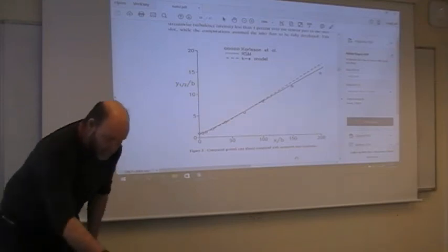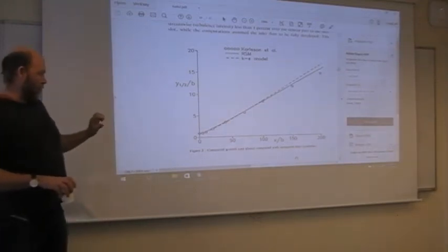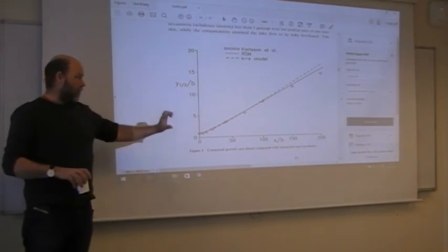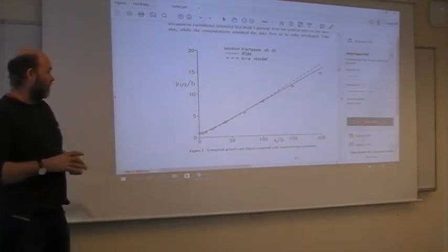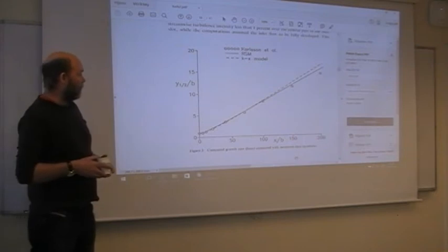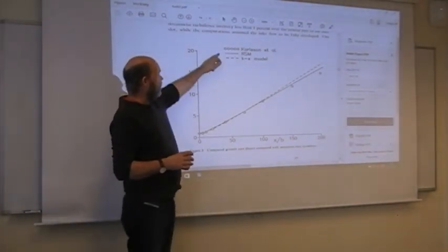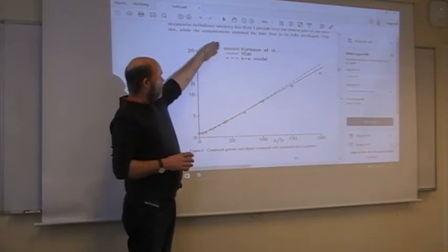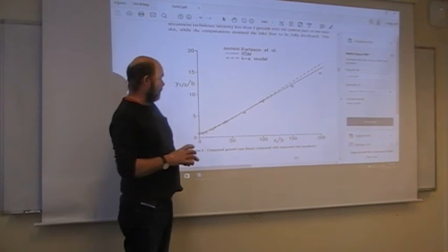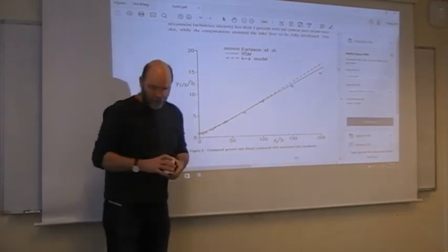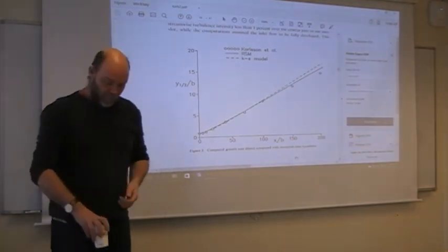So the growth, the height of the jet entering in the lower left corner, is here tested with a full RSM. And Carlson did some experiments, and then you had the standard K epsilon models. So, yes, clearly some differences.